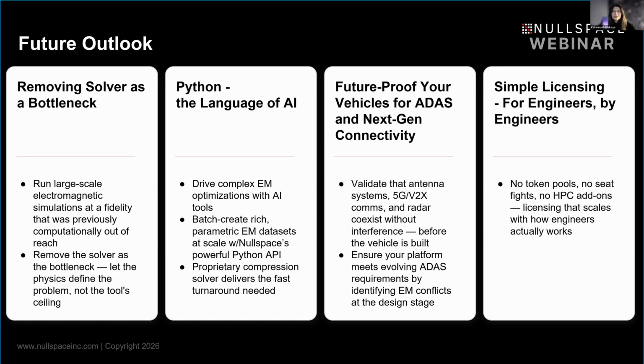Personally, looking at the results that we showed today, I wouldn't use this antenna on the glass roof case, because we have a significant shift in radiation and matching, a very big difference in radiation pattern, and a lot of nulls that look quite unpredictable. So we don't know where they will end up. For this case, I wouldn't use this antenna.